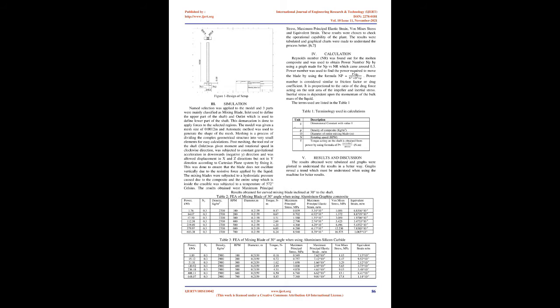Method. A. Design and construction. Here we have made a stir casting setup with 2 mixing blades and have performed FEA on it in order to obtain more information about the working conditions of the machine. Components were designed separately in SolidWorks software and the final design was generated using the assembly function of the SolidWorks software. In order to perform finite element analysis, FEA, on the mixing blades, the design was imported into ANSYS software.